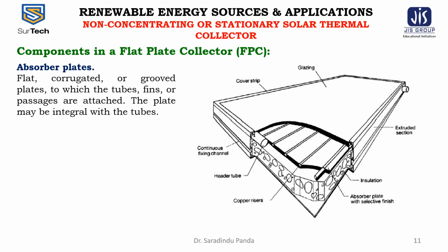It is possible to use several different design principles and physical mechanisms in order to create a selective solar absorbing surface. Solar absorbers based on two layers with different optical properties are referred to as tandem absorbers. A semiconducting or dielectric coating with high solar absorptance and high infrared transmittance on top of a non-selective, highly reflecting material such as metal constitutes one type of tandem absorber.